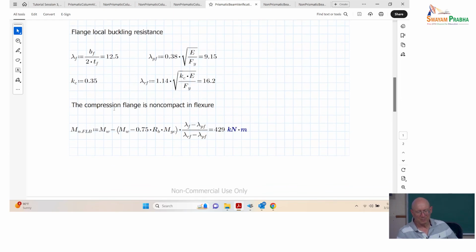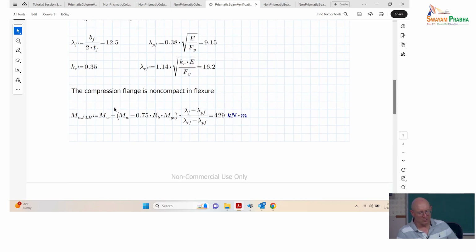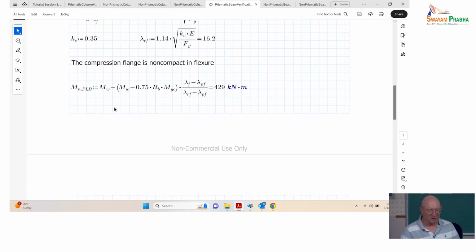And so the equation that is moving forward in the balance at AISC for the flange local buckling strength is what you see here. It's basically a linear reduction all the way out. There is basically a check that you'll never practically reach, where you basically say, I'm not going to allow that line to go less than the elastic buckling strength, but you'd have to have something really, really silly before you'd ever get there.